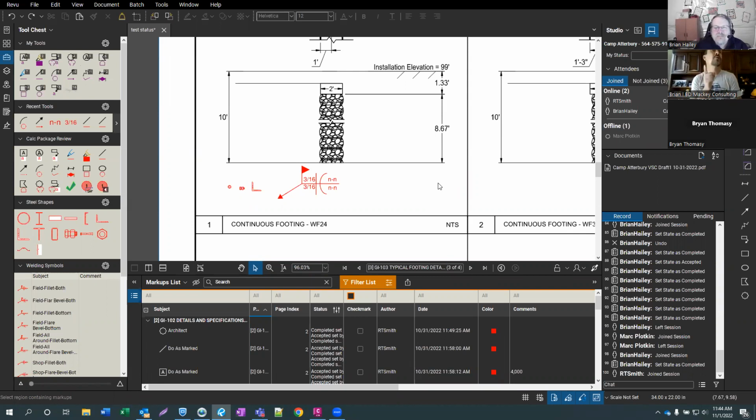So the Bluebeam tip that I always have, and what cracks me up, and this is where I always laugh with architects: did you know there's a disable line weights button for Bluebeam, so you don't even see line weights? Yep. That's the tool that I show. It's on the View tab. There's also a shortcut for it, but I don't remember what it is off the top of my head.